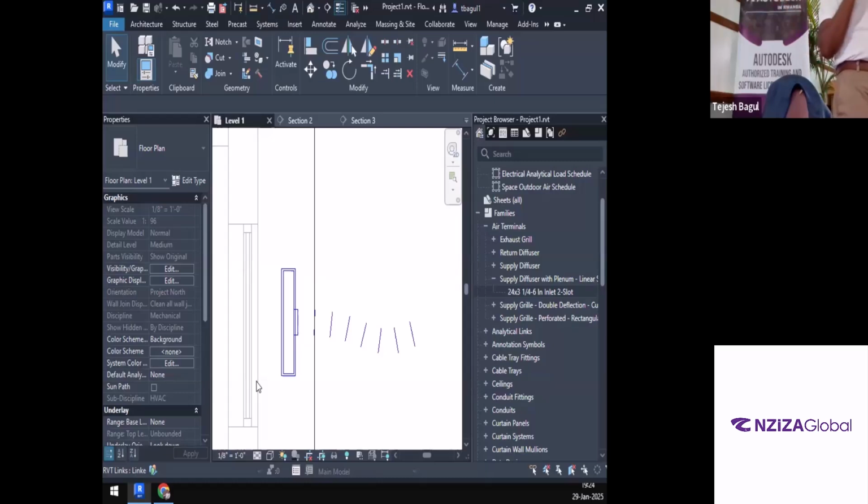If you have the standards of writing specifications or tenders in your market, make sure that it is specifically mentioned for the contractor to not exceed 5 feet length of flex duct. Right? Basically, we are talking about the fan power. The more pressure drop there is, the bigger the fan, the bigger the motor, the more power that the motor will consume. All right?